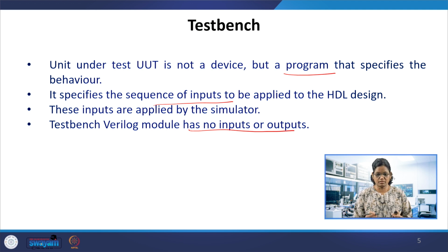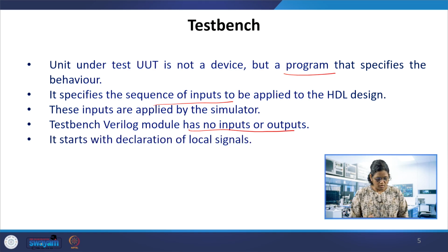Instead of that, the variables will be declared: the inputs, the outputs, what we are going to use. Those inputs are the Verilog module inputs, and especially the design inputs, and the outputs of the design will be considered for the declaration. So there are no inputs and outputs explicitly declared in the test bench.